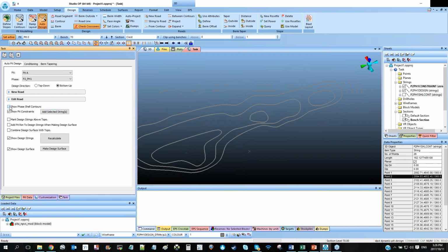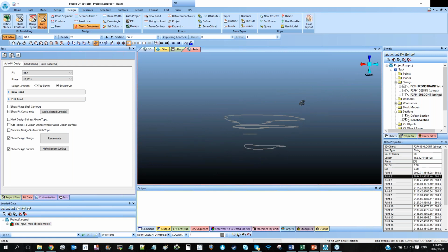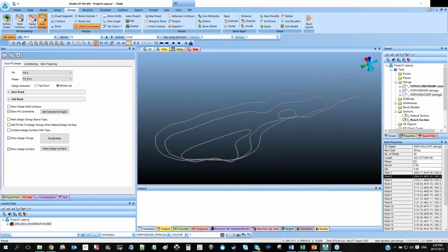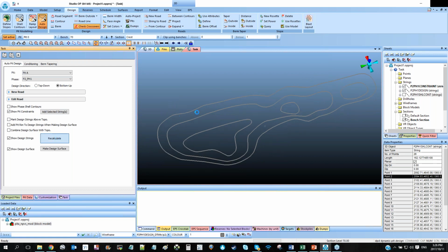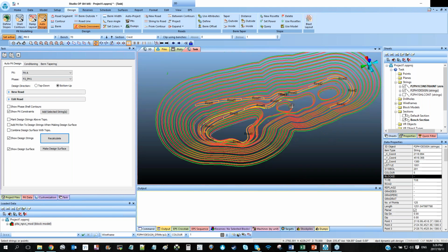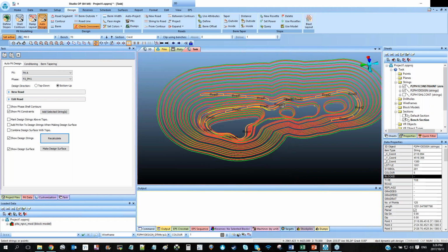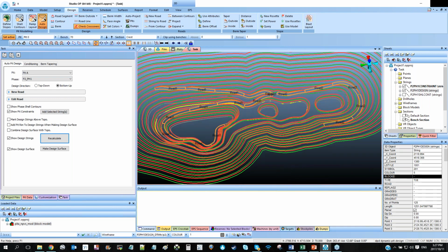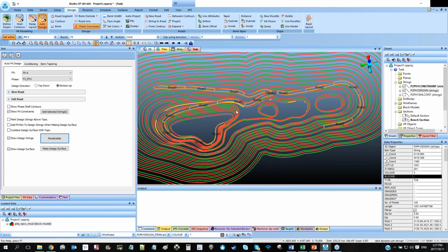And then if I now turn off my contour shells, so my contour perimeters, I can see that those guys have been defined as constraints, right? Now they have been defined as constraints, I can just say recalculate, and there you go. It's shaping up the pit quite nicely, right? It's already reading some of that information from my roads as I have defined initially on the ramp layout, right? So it's already picking up some of that instruction and combining with the constraints and already laying out the road